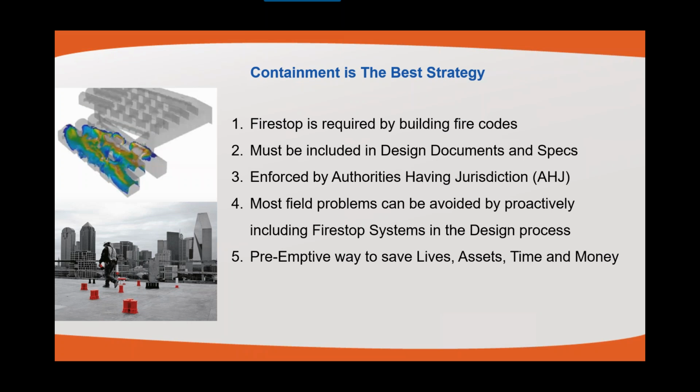So fire stops are required for containment issues. They're required by the building codes and must be included in your design documents and specs. They're enforced by the authorities having jurisdiction in the area, and most field problems can be avoided proactively by including these fire stop systems early on in the design process. And in just a little bit I'll show you what that will look like.